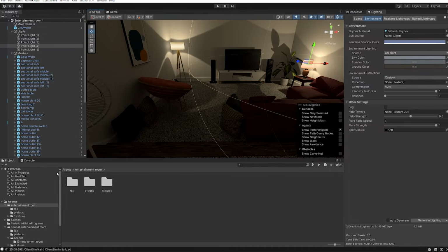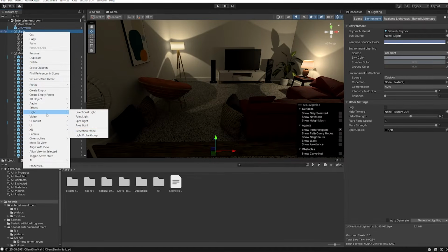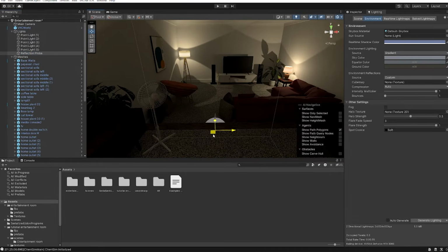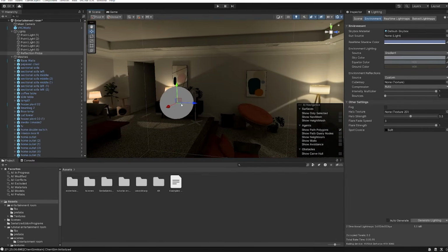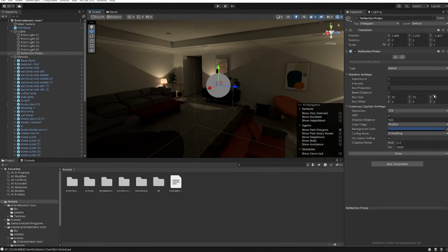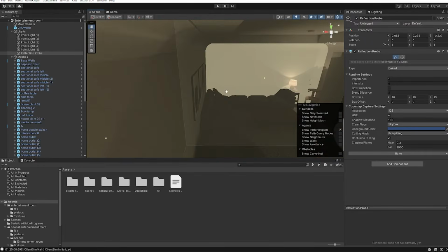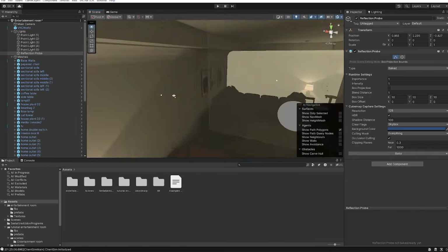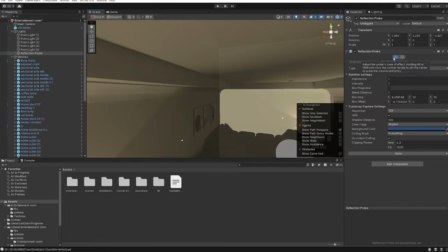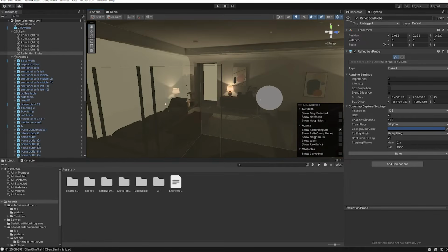Now we don't have any manual reflections in the scene because we haven't added any. So let's go ahead and add a reflection. Let's go to lights, right click, go down to light, and add a reflection probe. You're going to get something that looks like this. This is a reflection probe, and for rooms, I try to put it in the center of the room. This will determine what the reflections look like on the objects around it. Anything that is in this cube, and I'm pressing this button here to adjust the probe zone, is going to be affected by this probe.